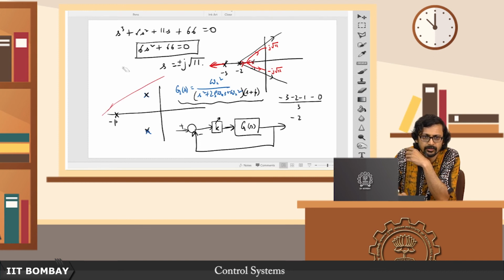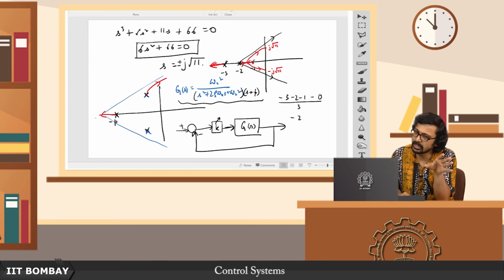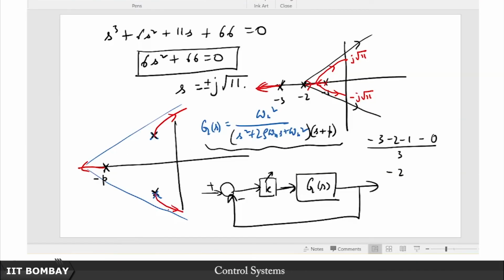Let me draw the asymptote with a different color. So probably you have some asymptote like this. So you will see that the actual root locus would probably look something like this. So even if it is good for this particular pole because it is moving more to the left half plane, and therefore probably making your system's response faster, remember for stability we just need one bad apple.